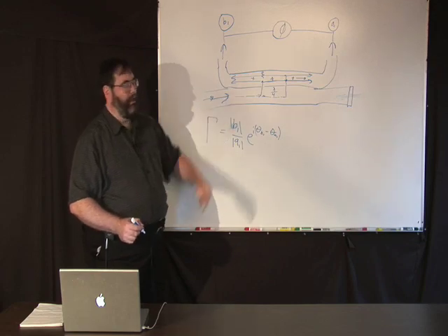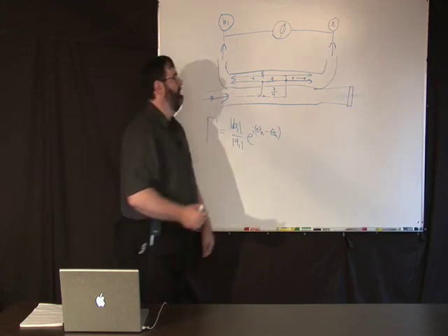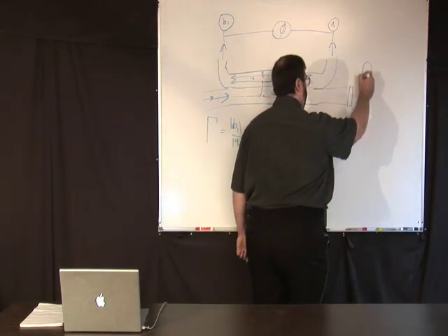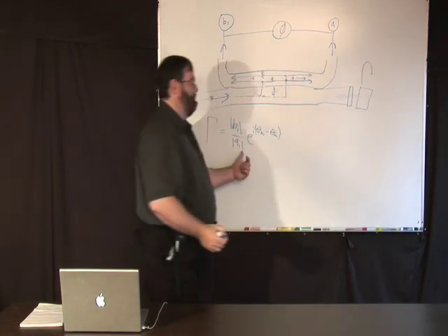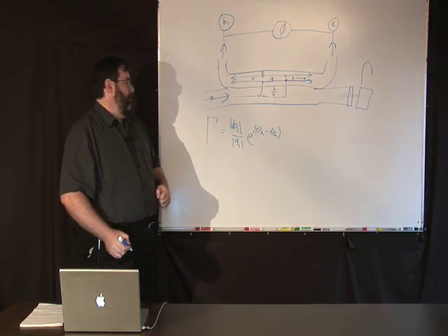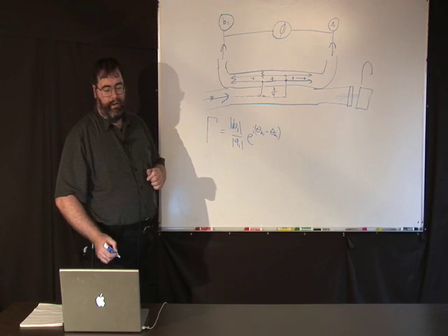So if this was an absolutely perfect reflectometer, you'd put your one-port device out here with its associated gamma, and you would just measure this, and that would give you the reflection coefficient. The problem is, you never have a perfect device.